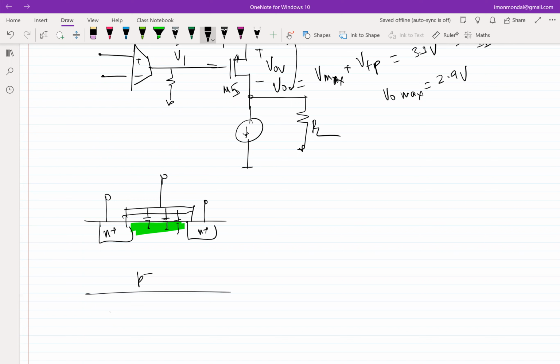But since distributed capacitance is difficult to deal with, we'll split the capacitance into two parts, one towards the source, one towards the drain. We club the capacitances together in such a way that they are referred between the gate and the source and the gate and the drain. Okay, so essentially we'll say there is a capacitance between these, and we'll assume that these don't exist. So this becomes CGS and this becomes CGD.